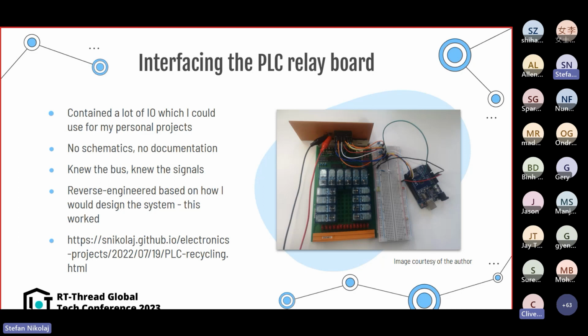So I'm just going to discuss how I reverse engineered this and how I knew what to replace with an RT-Thread microcontroller. Understanding the specific signals associated with this bus, such as the chip select, write signals, and byte selection, was essential for successful reverse engineering. And this serves as a valuable tip when approaching these reverse engineering tasks. If you have a clear understanding of the expected signals and operational methods, you can recreate that in a tiny fraction of the time it took the original developers to do so.